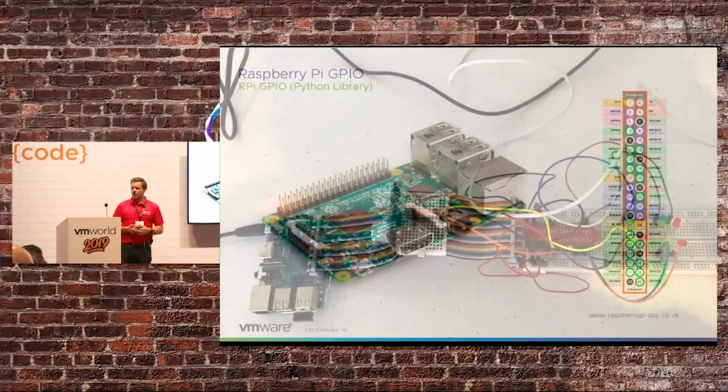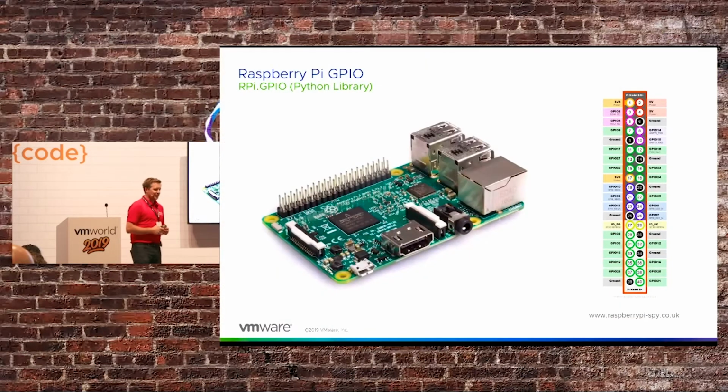So we were programming in different countries. And just to Nick's point here, the Raspberry Pi, and you'd be surprised how many people ask me why I put a cake into the Mars rover. I'm not looking at someone in the front row. But this is a Raspberry Pi. The pins on the top left, if anyone's seen these before, are called the GPIO. You program against these pins based on the map on the right. There's a mixture of ground, 3 volts, 5 volts, and then the rest of these you can program using Python code. There's a Python library which you can code against.